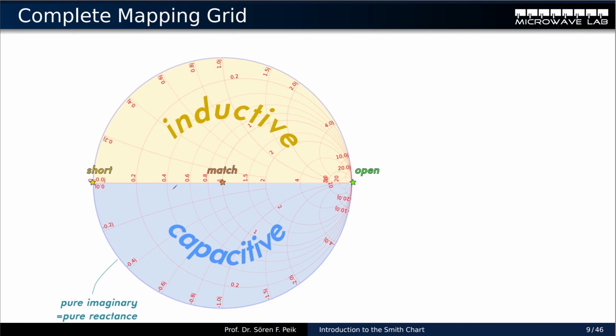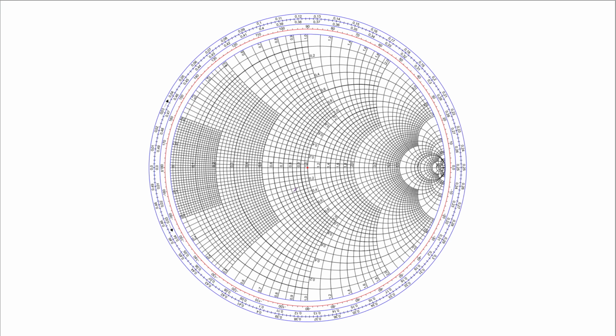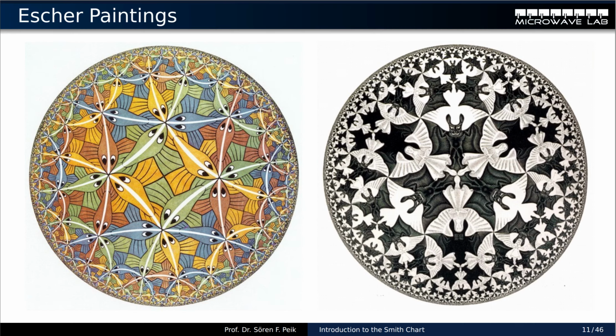So coming back to our example, when I have a real part of 2 and an imaginary part of 1, then I can use my real part circle as this, my imaginary part band is this, where they intersect, that's where my point lies. And now measuring this length and angle, I can find the gamma value. A real professional chart looks something like this. We're going to work with the professional chart later on. It has some more information on it, which we're going to use later on.